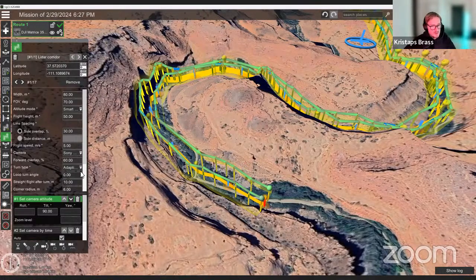And if you have a question about LiDAR payloads and LiDAR, how do you deal with that? Then the answer is simply that all you need for LiDAR is the field of view angle, actually. And that's enough to understand what should be the distance between the sidelines.